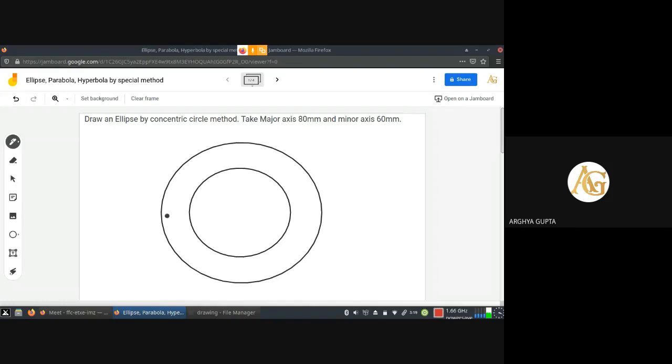center. Now once the circles have been constructed, you have to draw the axes, the horizontal one and the vertical one. Okay, so two circles have been drawn and the major and minor axes are drawn, and you know that the full angle for a circle is 360 degrees.